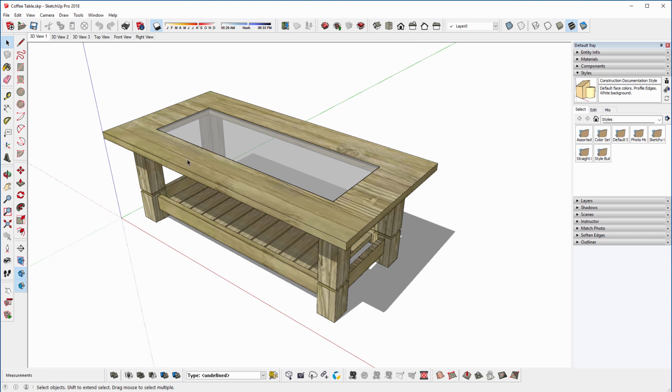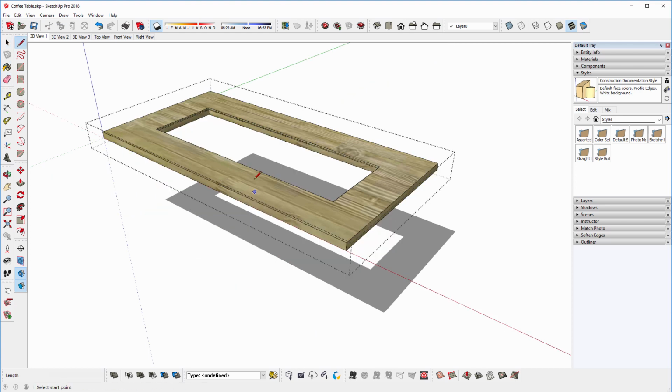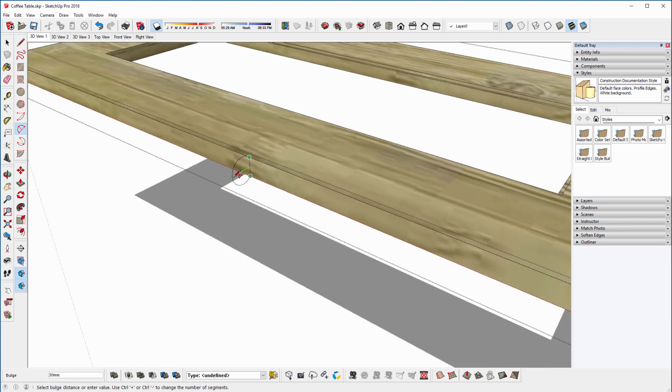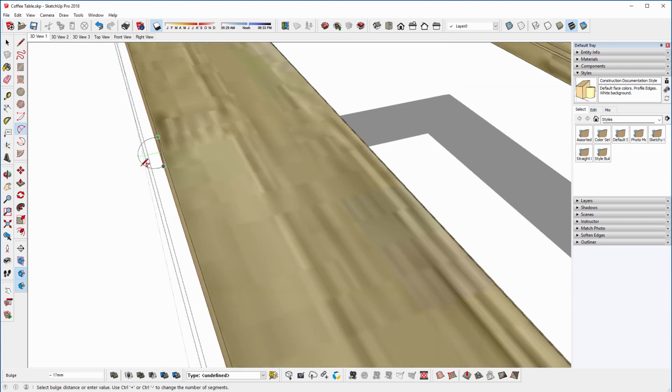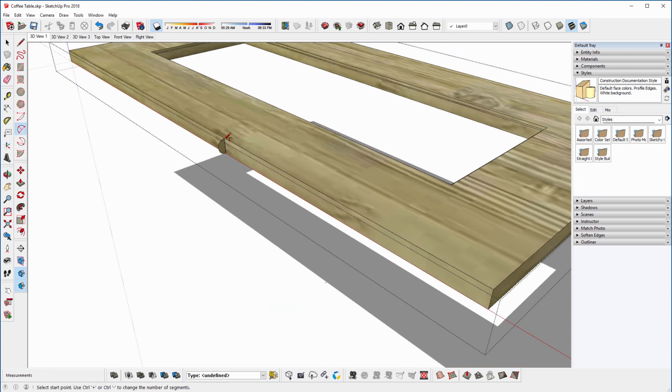So we're going to add a bit of a fillet around the top of the tabletop. So I'm going to double click on it, draw a little line down the edge, get the arc tool, or the 2-point arc tool, first point, second point, and then bring it away nice and big, and maybe then say, we'll find the half circle. So if you bring it in, keep bringing it in, it will eventually, with the right angle, find half circle. So the perfect solution for that.